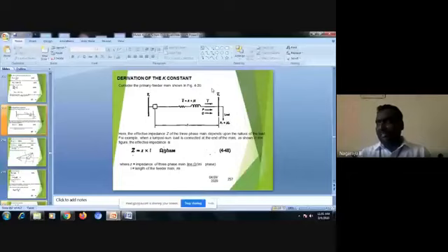At the receiving end side, I am taking the receiving end active power and receiving end reactive power. Both are different: PR plus jQR. In general, the active and reactive powers are P and Q, but when I go to the receiving end side, it is PR plus jQR. Both are different, you need to remember this. So I have Z amount of effective impedance for the three phase. Here I have shown the single line diagram, and three phase depends upon the nature of the load.